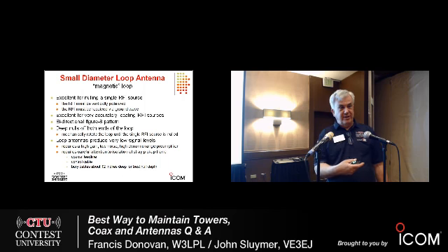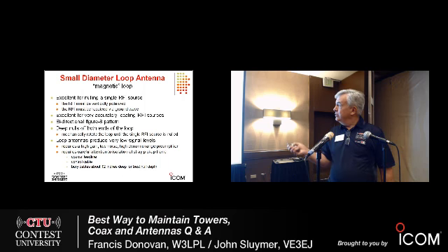It's kind of your job to find out where it is. I don't think it's reasonable for us to expect public utilities or a farmer to figure out which part of his electric fence is a problem, but we have the tools and knowledge to find the source, and this antenna is an excellent way to do that on 160 or 80.